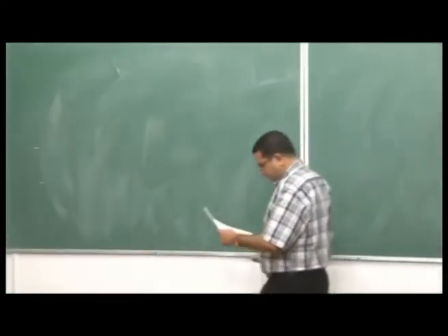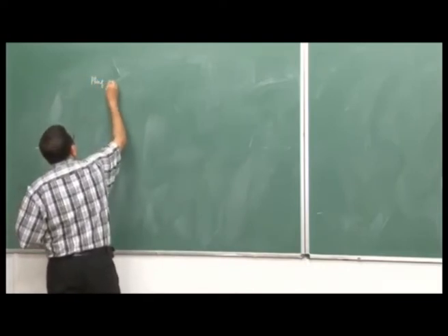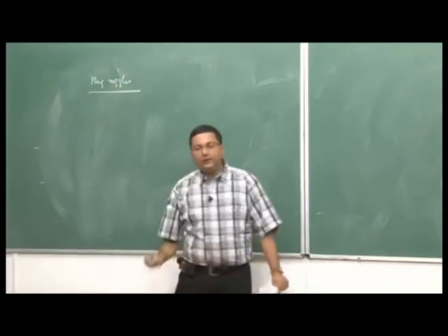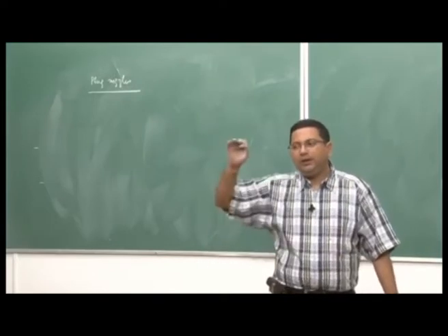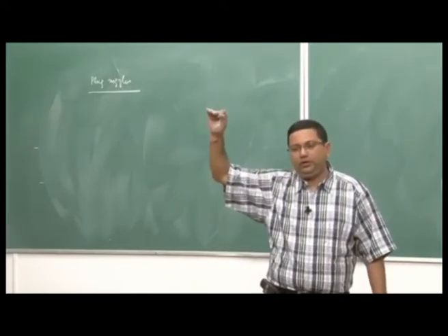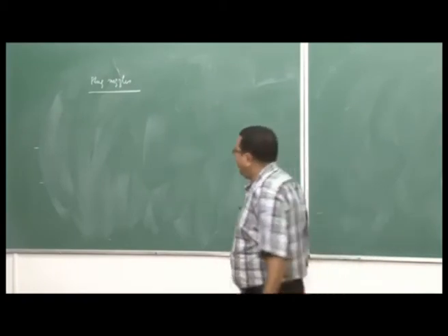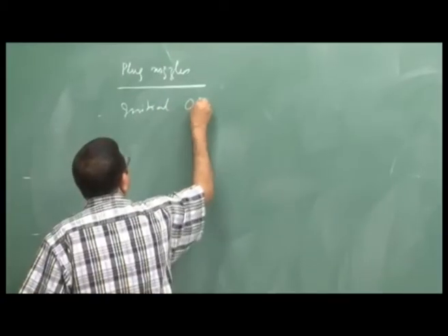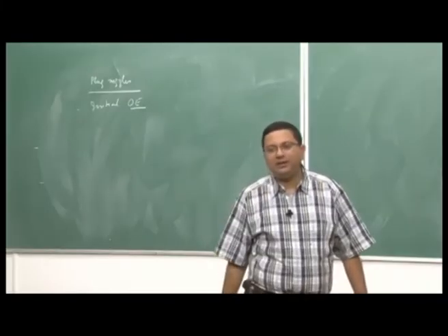So, first is plug nozzles. Okay. What did we say then? Our design philosophy is that we design the rocket for a higher altitude. So, during the launch it is over expanded, right. So, we have initial over expansion and we know that this over expansion is going to bring in some losses. We want to minimize this loss.